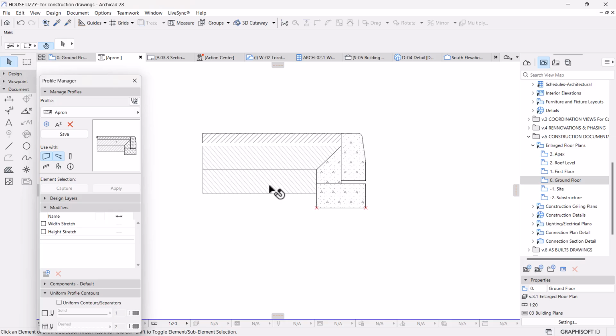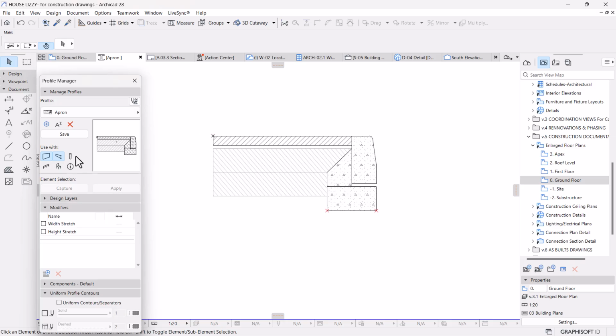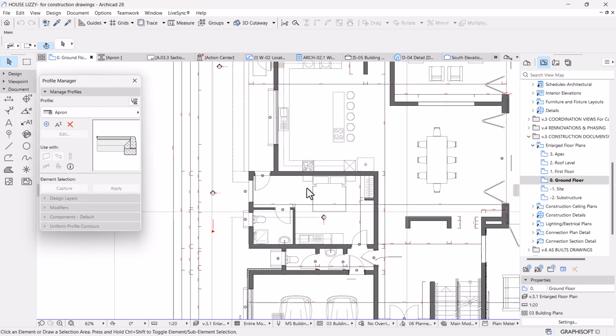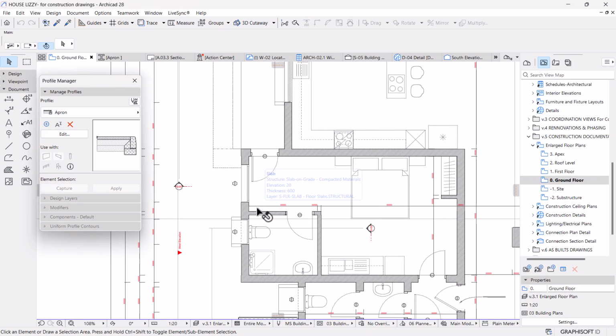All right, so what we want here is, we still have, I can see the arrow here. We need to cross check here. There's an arrow there. Hit save. It's going to be used by using a slab, the beam and the wall too. So the best way is to use a separate or a different tool. If you use wall to wall, it's not going to butt nicely. It will create some bit of a glitch of material. So I'm going to use the beam to achieve this.